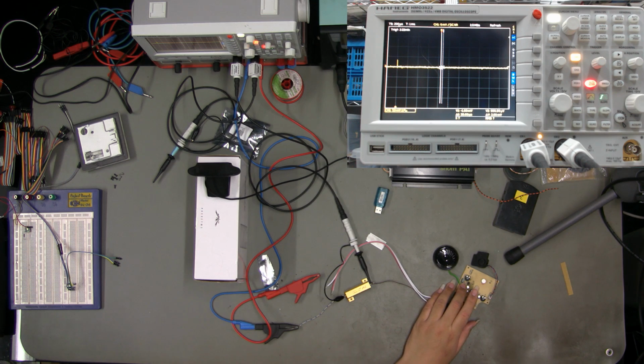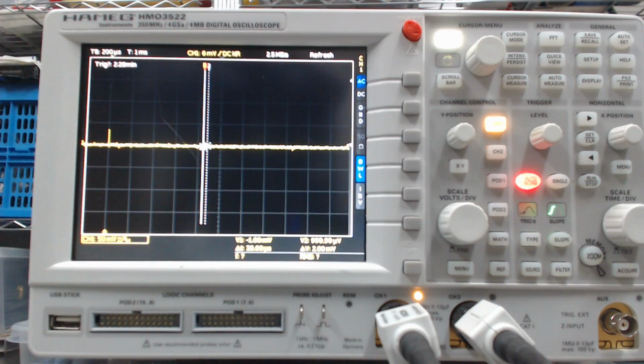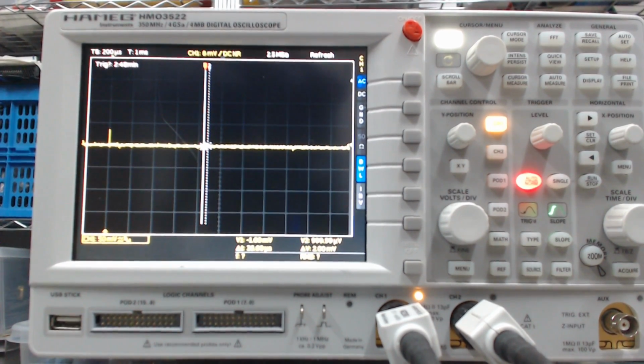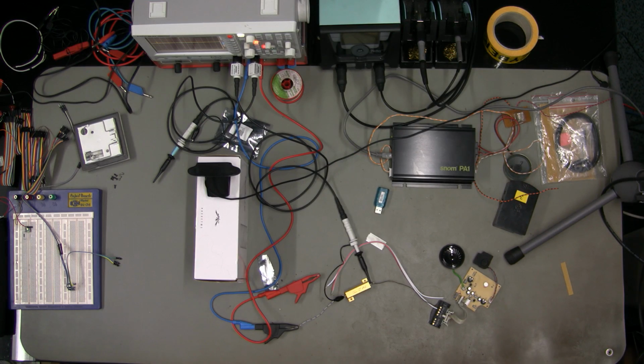And I set the oscilloscope to AC coupling, which filtered out the DC part, which was the base current this module draws. And with that we just saw the sound waves. I then played a sine wave form on my cell phone and put it close to the microphone, and we were able to see the sound wave.